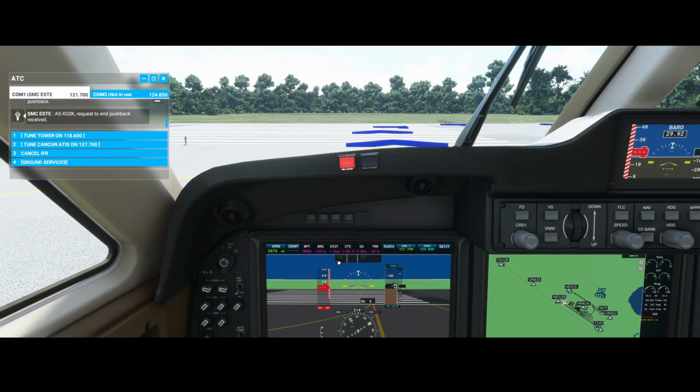And you can see that by switching on the flight director, two things are changing. The level is set, which makes sure that we're doing the climb, and the pitch is set because we want to climb to the altitude of 7,000 feet. And you can see that, let's switch off again, there's a nice pink arrow being displayed.